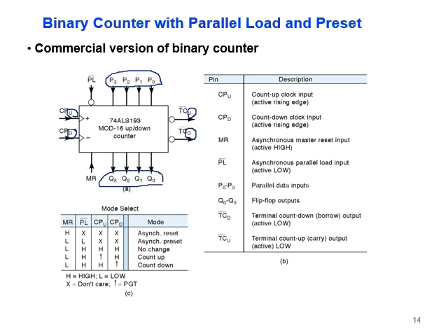Now this is the opposite of the previous one. Here it's triggered at low, not at high. High means 1 and low means 0. So this is the reset. When it is high, it means, regardless of what we have, asynchronous reset. If it is low, we have different options. If PL is low, then asynchronous preset. If all of them are high, it means 1 1, no change. If the down is high, and there is a rising signal on up here, then you are counting up. If the opposite, we are counting down. Very easy, almost the same, the same principle.